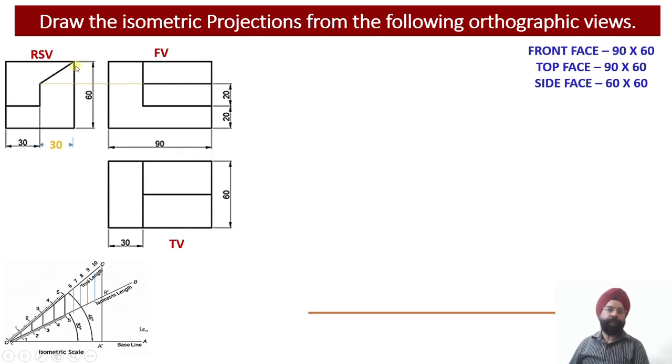So from the top, it will appear to be a rectangle. So this rectangle is the apparent shape in the top view. Even if we are looking from the front, this rectangle is again the apparent shape. This is again the apparent shape in the front view. Whereas if we look at this particular surface from the top view, this surface which we have obtained over here will be the apparent shape, and what is this surface? This is the surface which corresponds to element number 1, corresponding to which the first ring we are going to draw over there. So this surface will be 30 millimeter by 60 millimeter. So this is this 30 millimeter which is appearing over here, and it is this 60 millimeter length which is appearing at this particular juncture. So this way, we have obtained the breakdown of 3 elements over here.